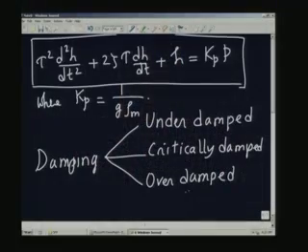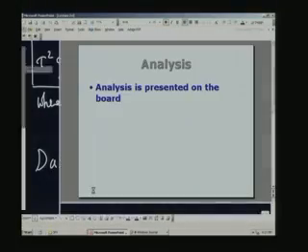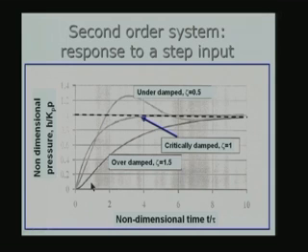This can be seen from the figure I am going to show on one of the slides. So, we have a second order system. We are talking about the response to a step input. This is just like what we had in the case of a first order thermal system, when we suddenly changed the temperature of the surroundings. Here, for example, initially the pressure is the same on the two sides of the U tube, and suddenly the pressure on one side is taken to a value equal to 1. This dashed line shows the step input in this case.